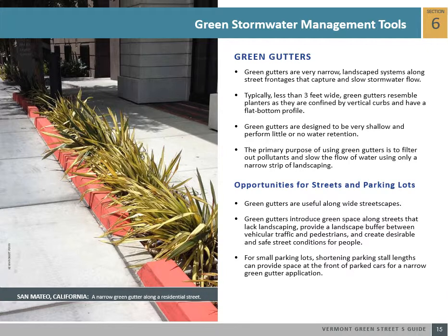Green gutters have many active transportation, urban ecology, and neighborhood enhancement benefits. They can act as buffers between sidewalks, bike lanes, and vehicle travel lanes, contributing to the safety and walkability of a street. They're an excellent method for cleaning water prior to entering a downstream water body, and are superior to pipe and gutter systems for this reason. They can minimally help with placemaking and provide community public space. Green gutters typically cost between $8 and $25 per square foot, depending on retrofit conditions or new construction.